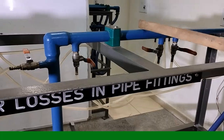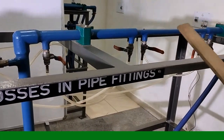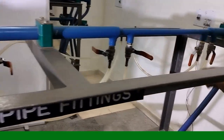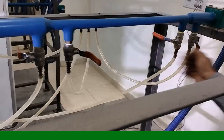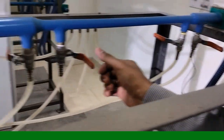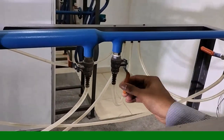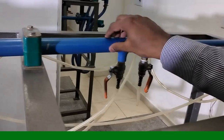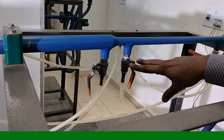All the pressure tappings should be closed. Only that particular pressure tapping should be on. Suppose we are going to conduct the experiment on sudden expansion. We have to open only that particular pressure tapping. Remaining all pressure tappings should be closed. The procedure will be the same.